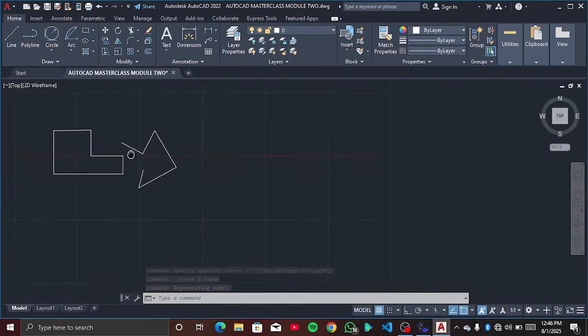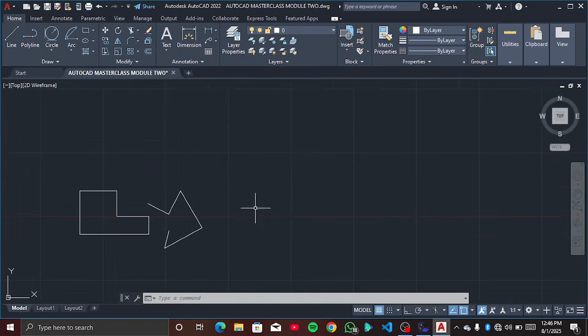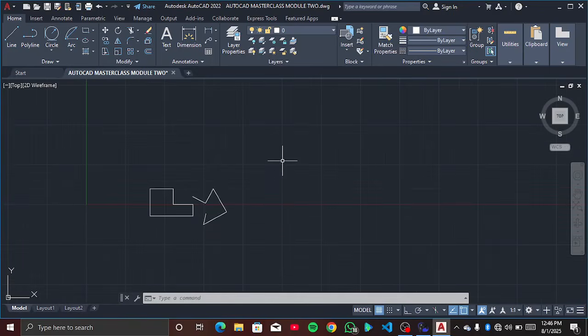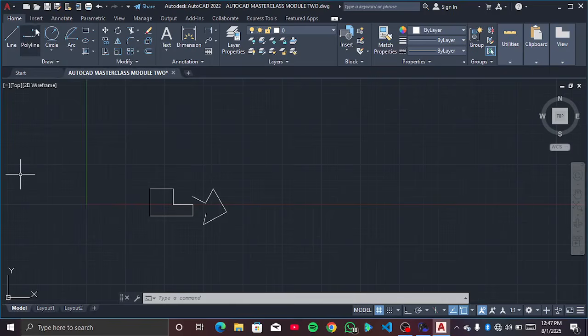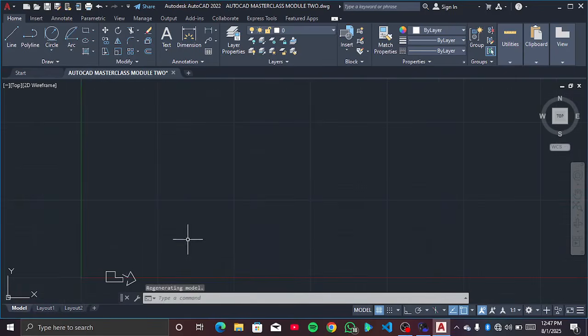And then another thing about polyline, okay, let me explain this one. This one can be a bit difficult to understand, but just follow me here. From the name polyline, you can even see the element where this thing is drawn. It's not just a straight line. A line can also be a curved line, zigzag, anything. So you can also add an arc with a polyline. You can see the way the element is, this line, then it curves like this. So you can also do something like this. Let me show you how to do it. It's called a polyline for a reason.